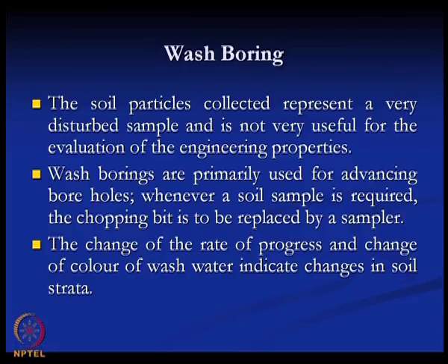Wash boring is primarily used for advancing a borehole. Whenever a soil sample is required, the chopping bit is to be replaced by a sampler. The change of rate of progress and change of color of wash water indicate changes in soil strata. So, the color of the soil-water mixture gives an indication of a change in soil strata.